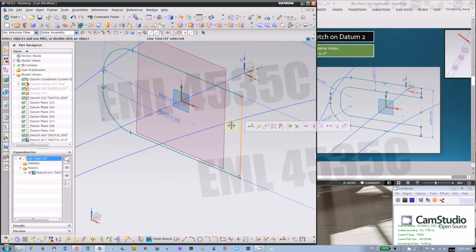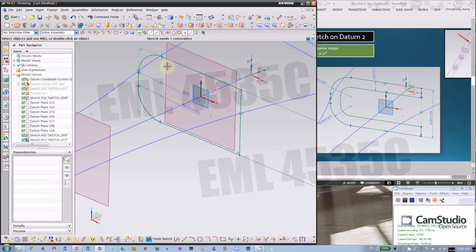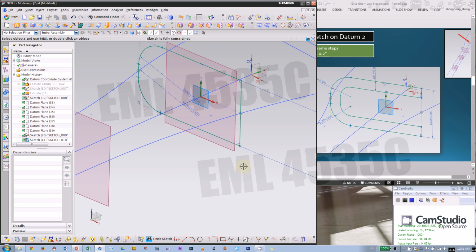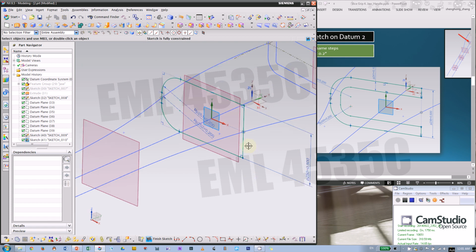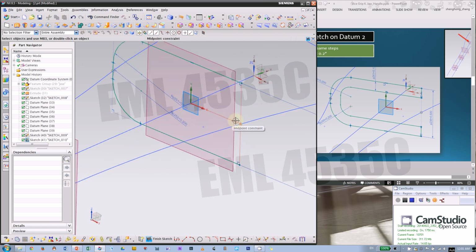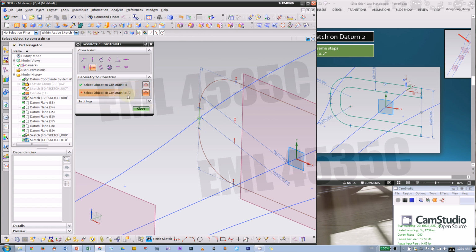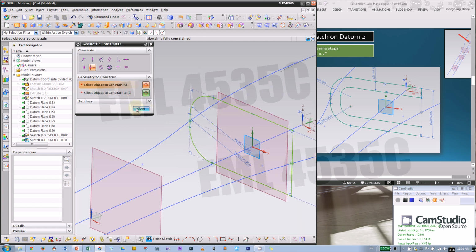Okay, I'm using the quick menu constraints. Then vertical line to midpoint. So midpoint for either one. Then we can offset. This one is probably not good, because once I trim this off, it's gonna delete that constraint. So better to have this line centered on the origin.